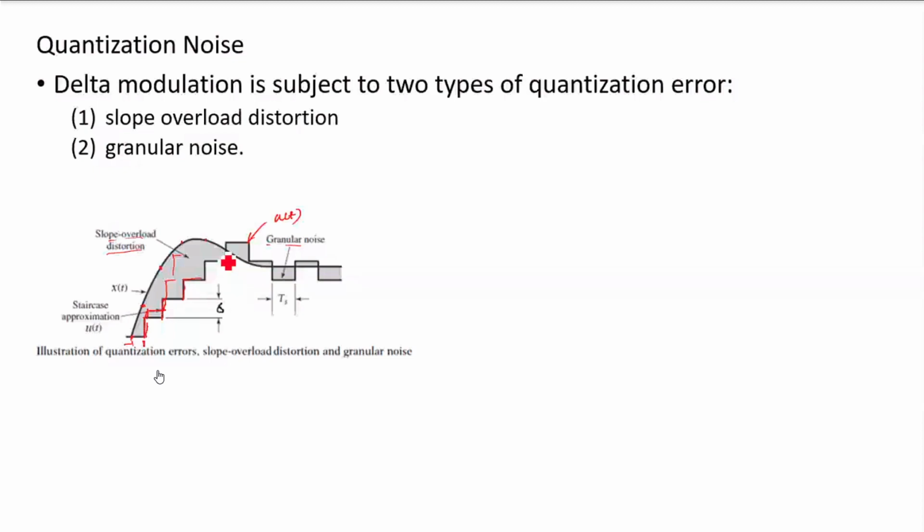So my system should be such that if there is a steep slope, the quantizer or the step size should be increased continuously. If there is a settling time for the signal, where the signal doesn't change, then we have to decrease the step size, right? So we have to find a way to do it. Who can tell us? One system which can do that is the adaptive delta modulation scheme, right?